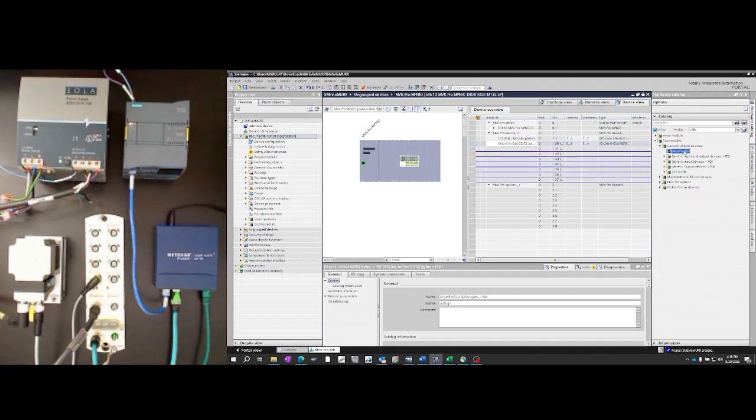I will click and drag a deactivated port identifier to each of those remaining ports. Now that we've got deactivated on all other ports, the last thing that's a very useful tool is to add a web server for diagnostics and configuration to the option ports below.